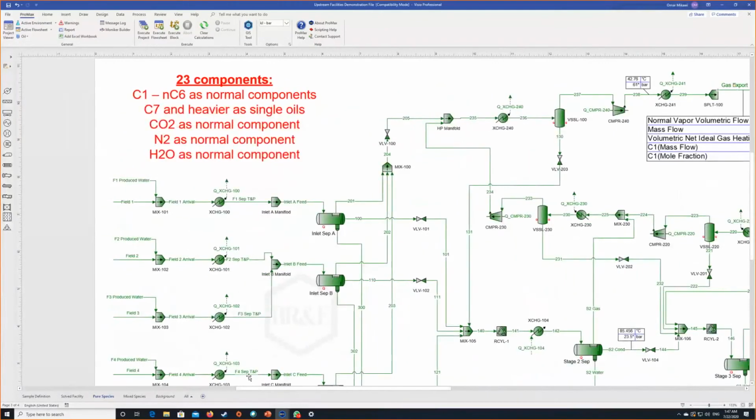The allocation report in ProMax is done by utilizing our latest addition to our ProMax toolkit, which is in ProMax 5, which all of you guys should have available, which is the mixed species tool. Basically, you can create an environment, or a component in the environment, that has a certain mixture of components. This is especially useful for when you have blended amines, for example. A lot of you guys are sour gas technicians or sour gas process engineers. If you have an amine blend, that's what the mixed species would be useful for.